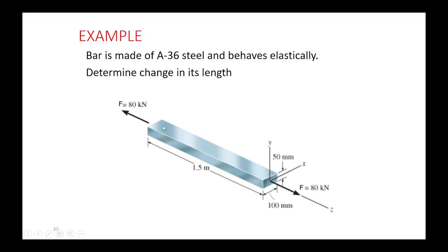But the condition, you know, in elementary stress analysis books or corresponding courses, we say that the cross section selected is sufficiently away from the surface where we have the load. Okay, not in the vicinity of the load, but sufficiently away from the surface.